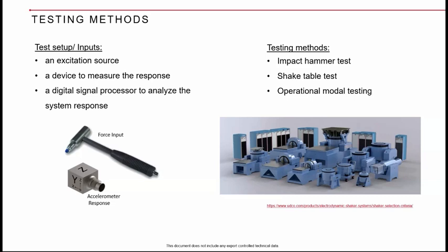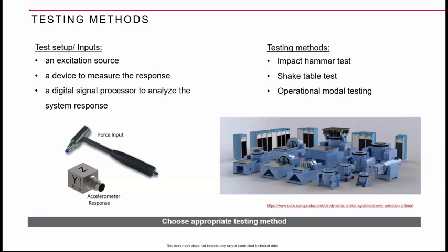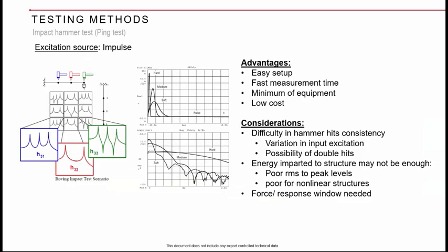So impact hammer test definitely has a limitation with respect to the kind of energy levels that it can pump in. The source of impact hammer test is the impulse, the ping you create on the object with the impact hammer. What is the shock pulse that it creates, what is the level of energy, and what frequencies are getting excited.